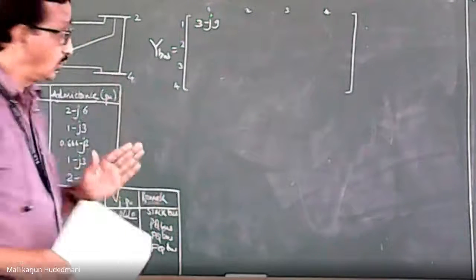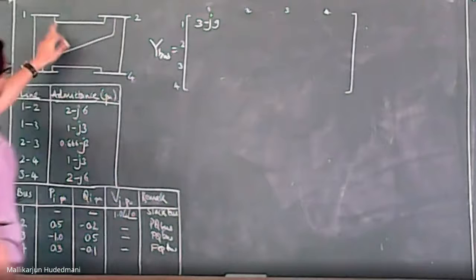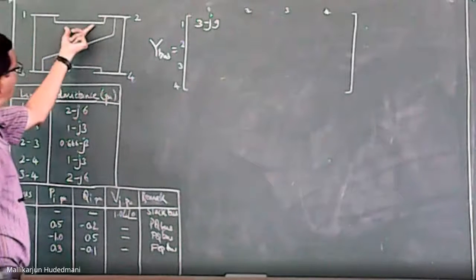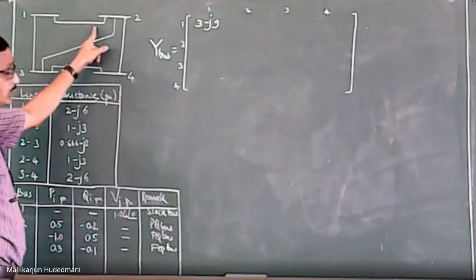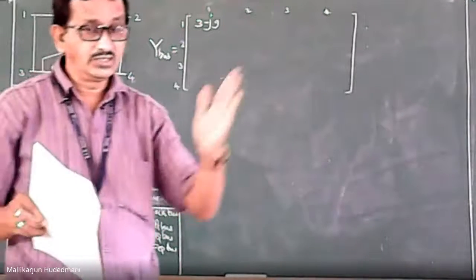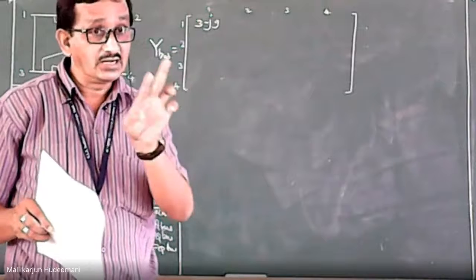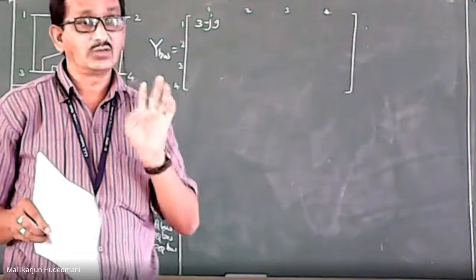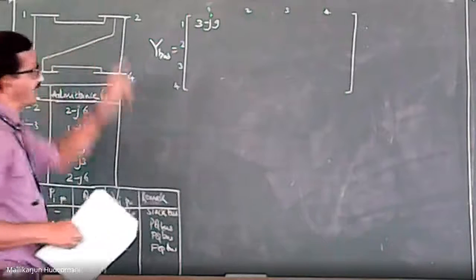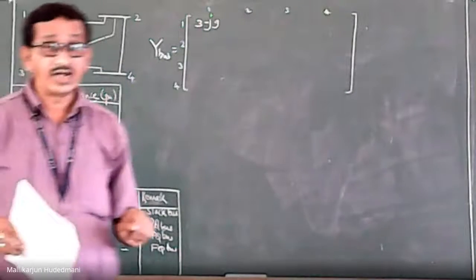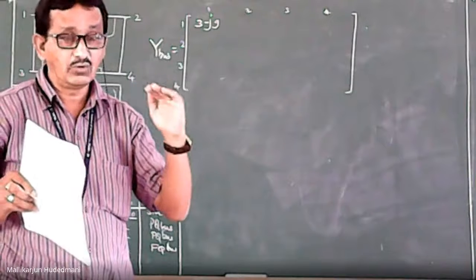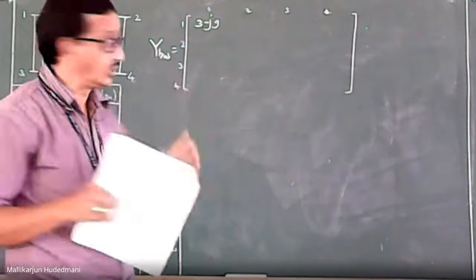When I apply nodal analysis between these two buses, the current flowing from 1 to 2 is V1 minus V2 into the elemental admittance Y12. When I separate them into V1, V2, V3, the second bus becomes negative. Therefore, when I take V2 outside, Y12 remains as the negative of the admittance of the connected line. Hence, off diagonals are the negative of the elemental representation.